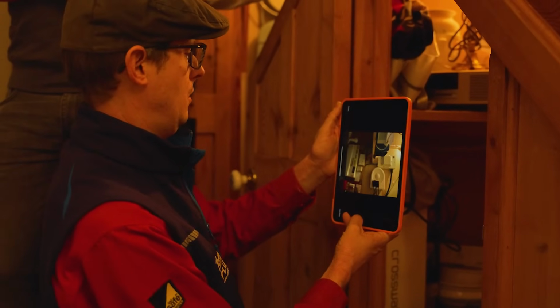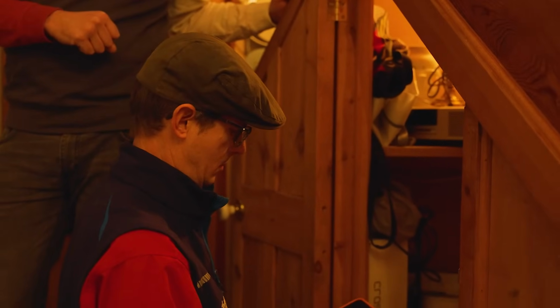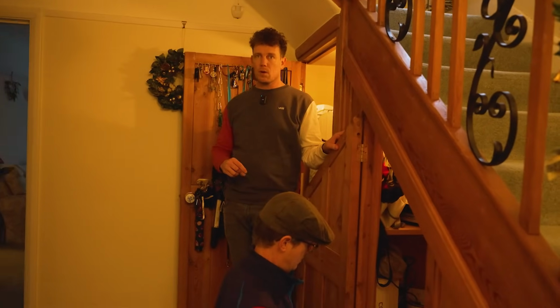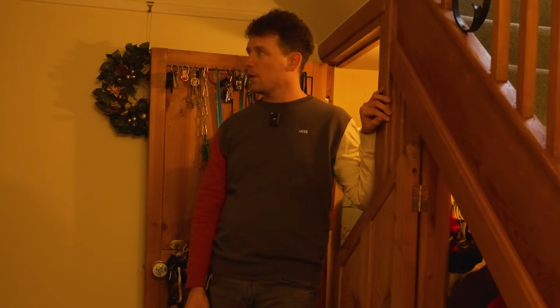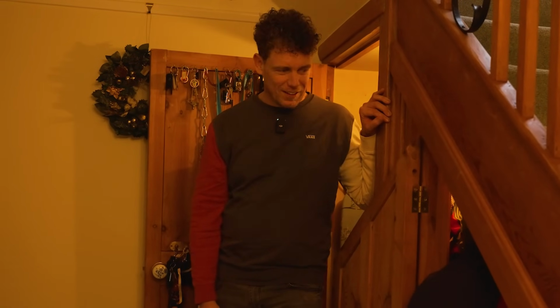So what he'd also be doing now is a maximum demand calculation, which is where you work out how much electrical draw the whole house takes entirely, so you don't pop the main cutout fuse whenever you run the heat pump, which is exactly what your first installer didn't do, which is why your main fuse kept going out. Left us in the dark.